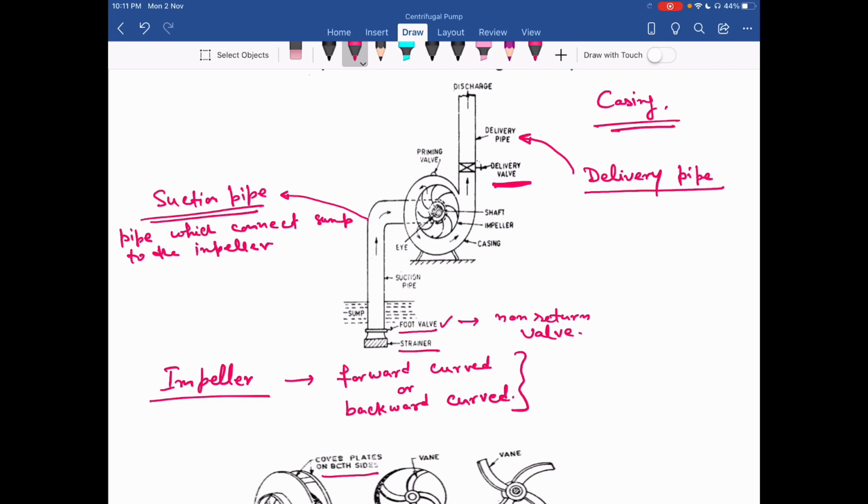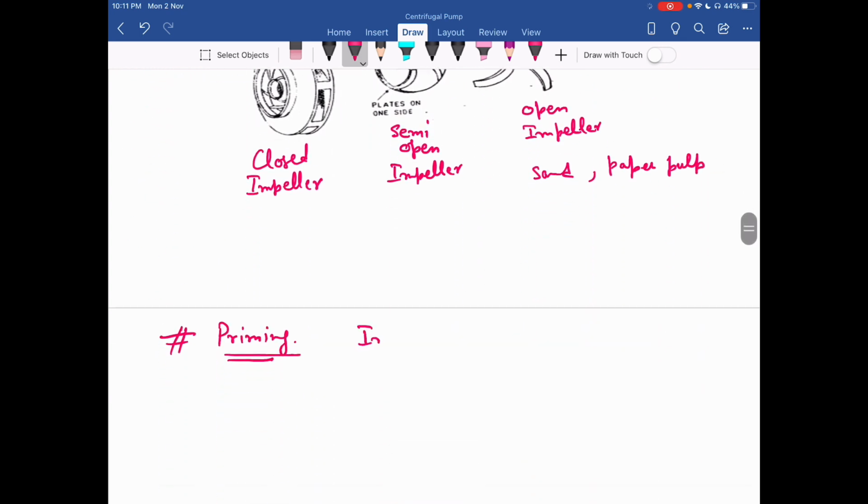In the impeller, I have only air now. As long as the impeller rotates in the air, the centrifugal head developed by this forced vortex will be proportional to the density of air. So whatever pressure is produced depends on the density of air.